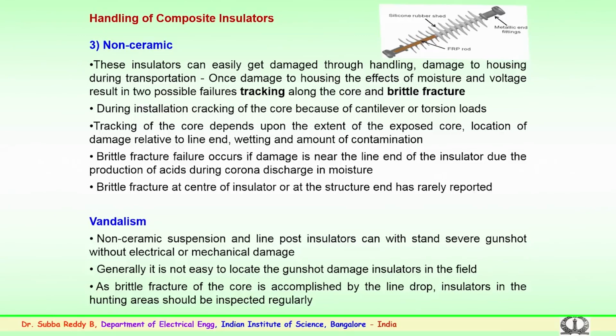Again this could be because of the end fittings, because of the corona, because of the water seepage, because of the crimping at the ends. So, these could be the reasons for not many failures observed at the center of the insulator or at the structure.